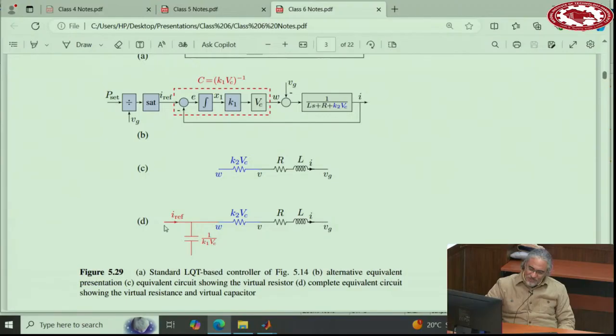If you look at this system, and let's say something happens here in the grid, like what we said before, if this capacitor can respond properly to what happens here, it will give inertia, because what does a capacitor do? A capacitor stores energy, like the rotor that is rotating and stores kinetic energy.